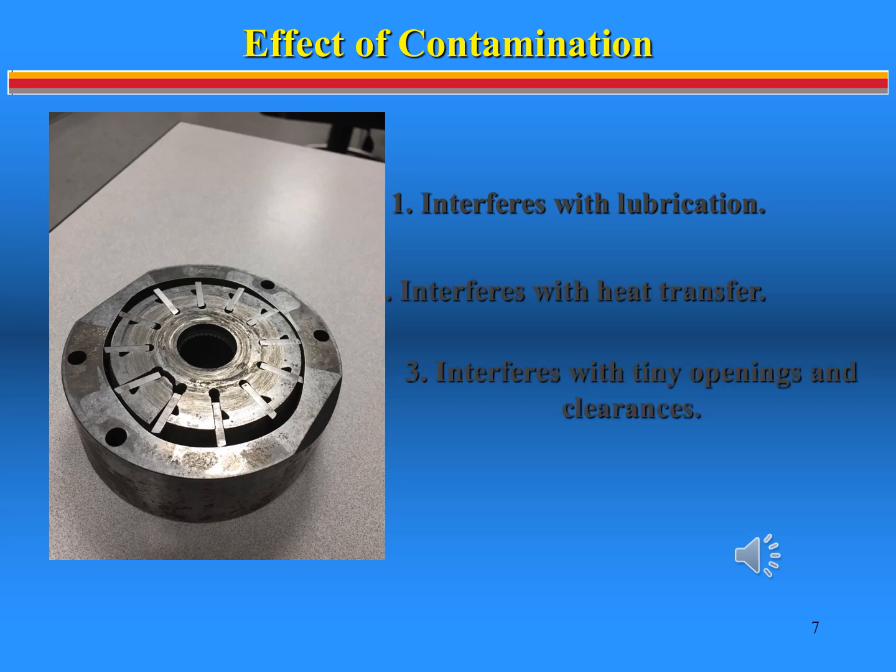By controlling the level of contaminants to acceptable levels, you can eliminate as much as 75% of the potential causes of system failure. This is extremely important when you consider high equipment cost and our dependence on today's sophisticated and complex hydraulic fluid power systems. The reason dirt plays a large role in system inefficiency is simple. Dirt behaves like minute abrasive gravel, which travels through a system and internally deteriorates and destroys sensitive hydraulic components, causing reduced efficiency and eventually system failure.